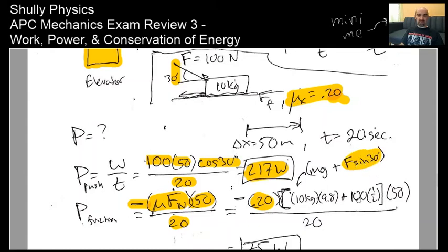Okay, so the force is 100, sine 30 is 1/2. So that's the total normal force. So that's where that comes in. Got mu times the total normal force. Okay, don't forget those components in there, especially when you've got a force pushing downward or lifting upward. Don't jump to that conclusion that normal force is equal to weight. That's something that'll trick you.